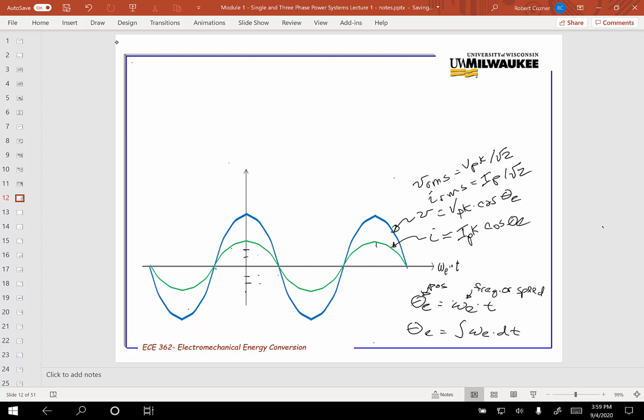Now, knowing that, in this class we're only going to talk about AC systems operating in the steady state. And when you go into the lab and you make voltage and current measurements on AC, you will be measuring RMS. In fact, all meter measurements nowadays, like Fluke meters and things like that, are RMS or true RMS readings, which is the mathematical RMS, just the way I explained it with the DC system.